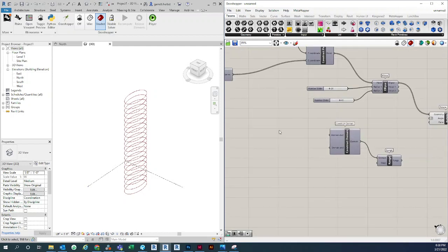So let's say we'll want our tower to start at 0 degrees. And let's just say for right now, we'll want it to end, well, let's create a number slider, excuse me, from 0 to 360. For those of you who don't know, if you hit a number and then dot dot and then the last number, this gives you a number slider between 0 and 360.